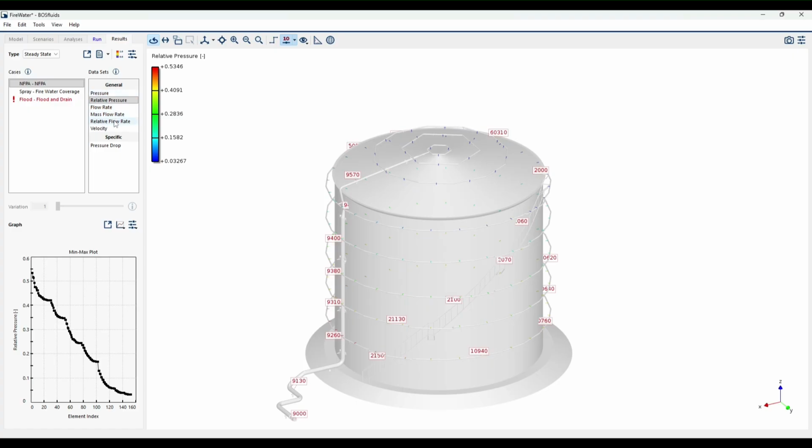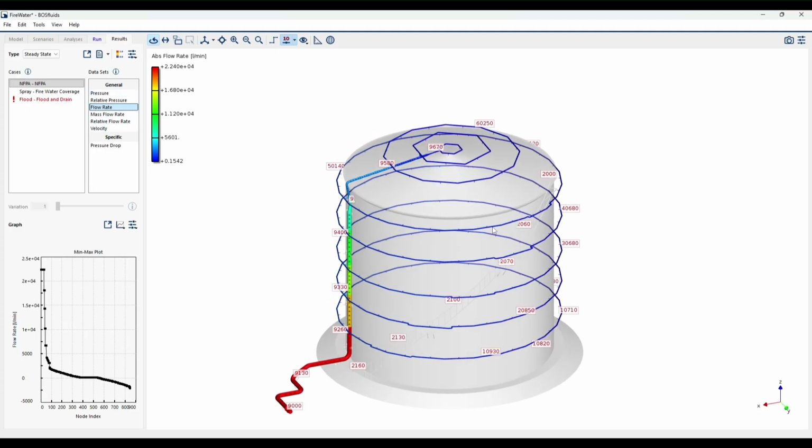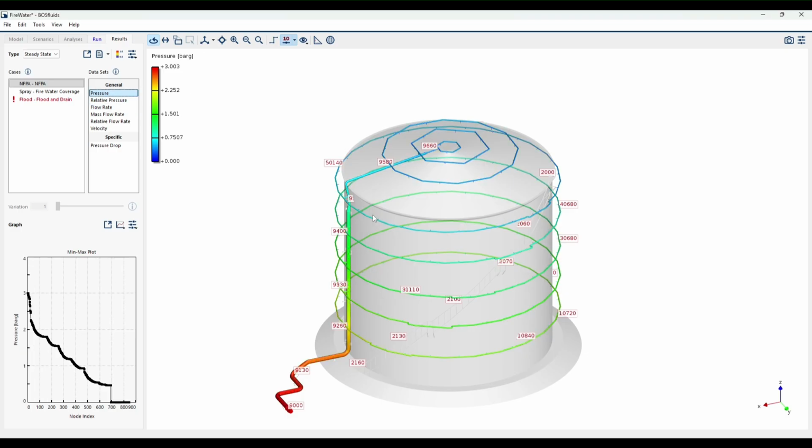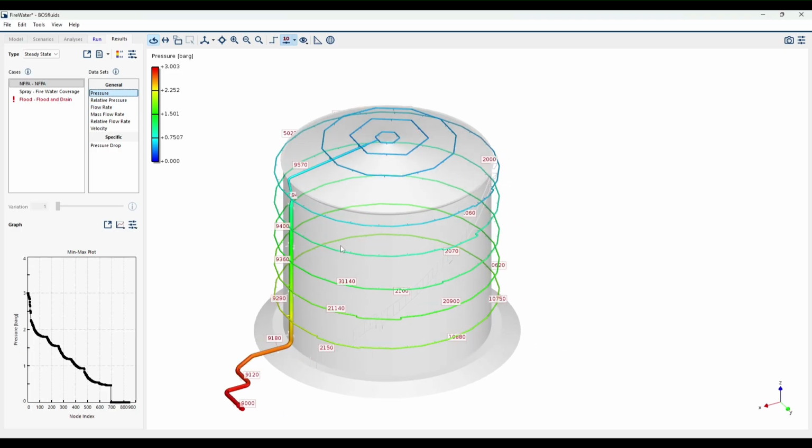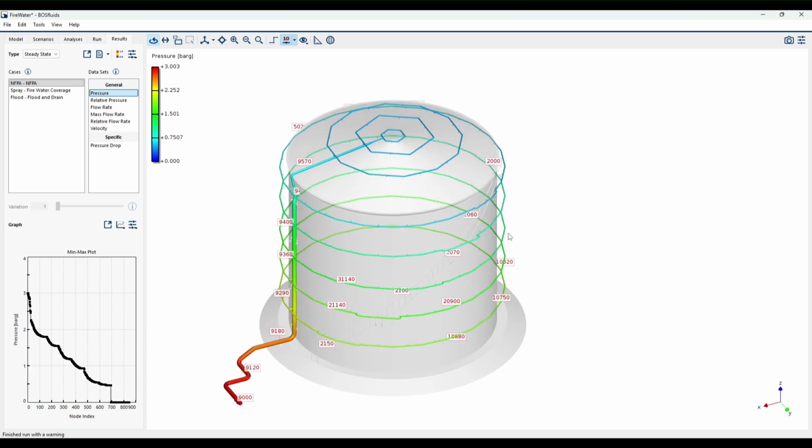The first one is the flow rate, the pressure. This is the pressure profile that we will need to reach the minimum flow rate. Above this, we will always reach the minimum flow rate. So with 3 bars in that supply node, we are okay.